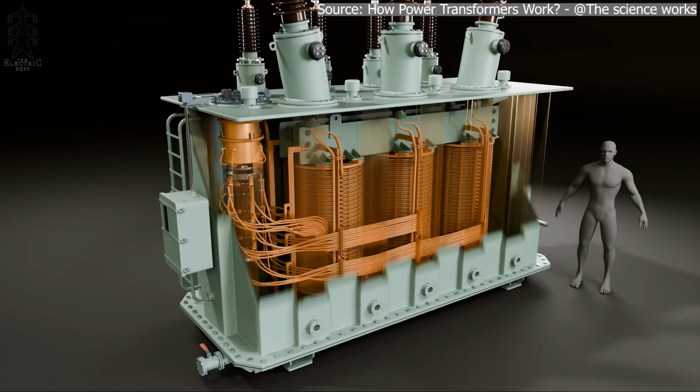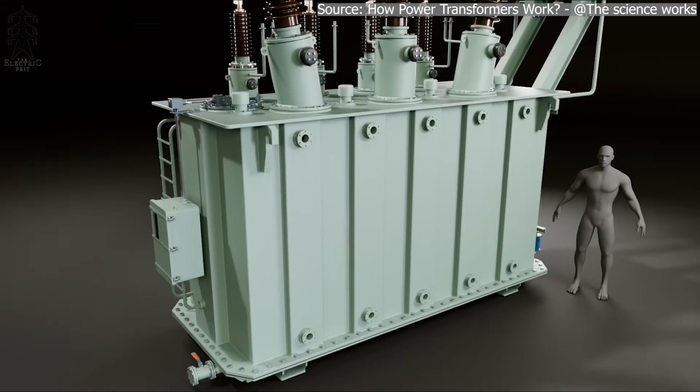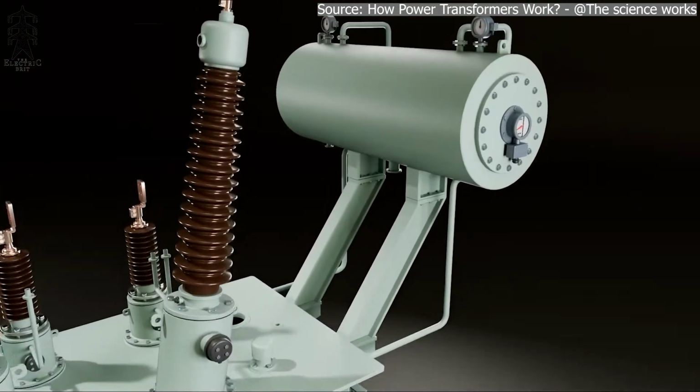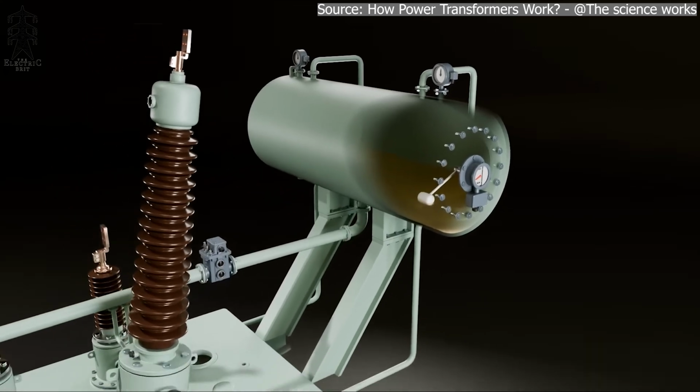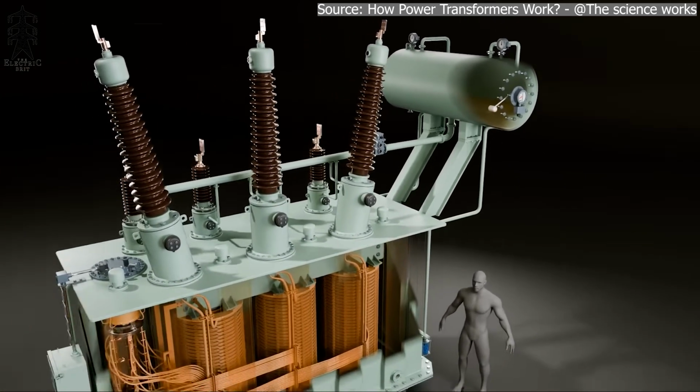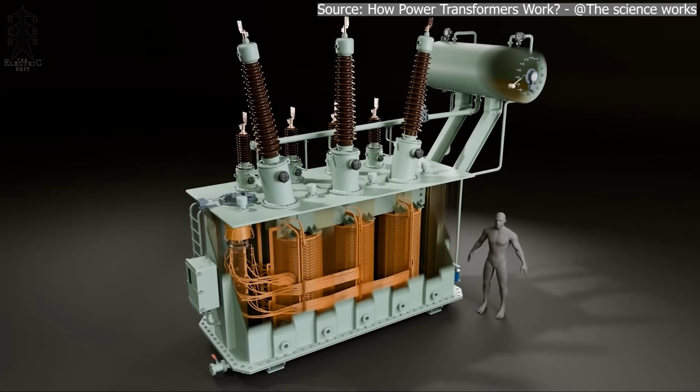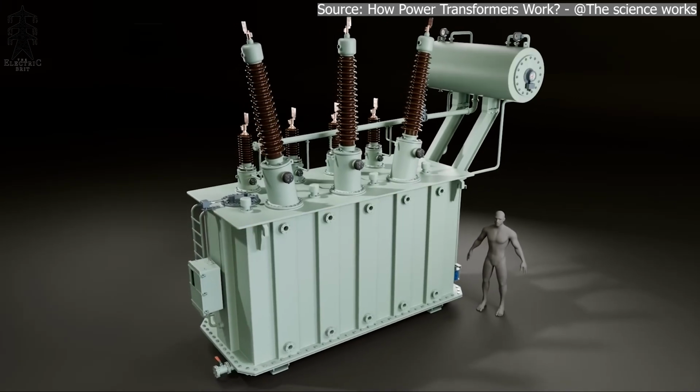We've mentioned a tank, which is the biggest and simplest part of a transformer, essentially a large tank holding all the insulating oil, with the windings and core inside. After that, you may notice a little tank high above the transformer. This is known as the conservator, and is essentially an oil reservoir that allows the oil to expand and contract as it heats and cools, without rupturing the transformer's main tank.